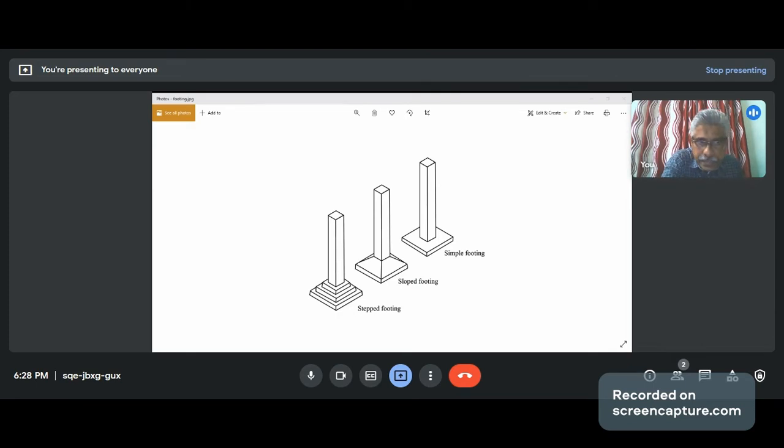So, in a numerical problem in design of concrete structures, when you are given the value of bearing capacity, you should understand that all these things are underlying it. When we do the concrete design of an isolated footing, we need not think about the shear failure of the soil or settlement of the soil. We need to use the bearing capacity as it is.